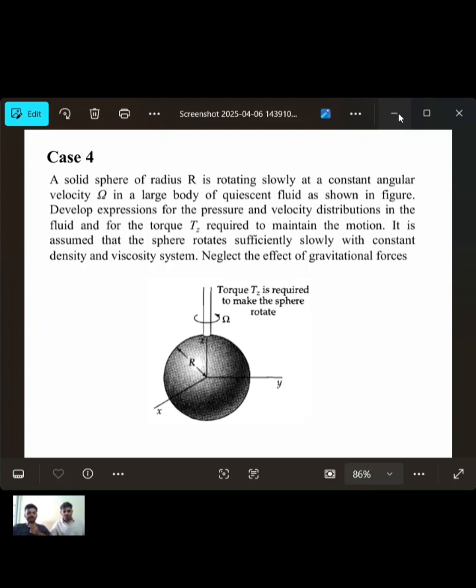Now moving on to the physical interpretation of the problem, as we have derived the velocity profile and the torque proportionality, we can show that the velocity decays and follows the inverse square law. That means the velocity is proportional to 1 by r squared, which means as we increase the radius, the velocity decreases by the square of the radius.